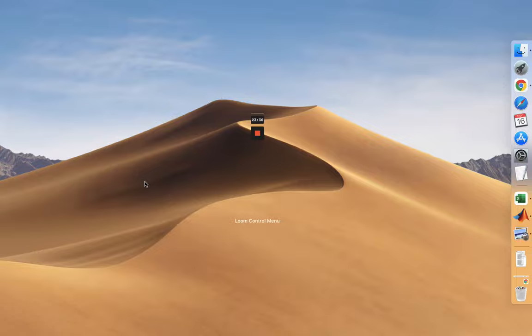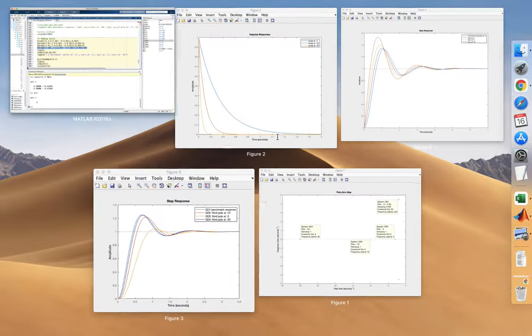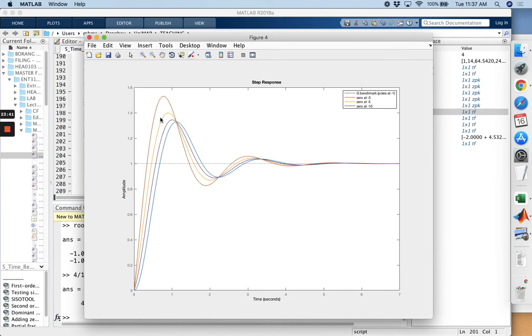So in this example just now, all of these plots are composed of a second order system plus 1 zero. The difference is only the location of the zero. Blue, no zeros. Purple, zero at -10, which is a distance away from the dominant poles at -1. The yellow is at -5, which is just enough. The distance is -5 as compared to the poles at -1.